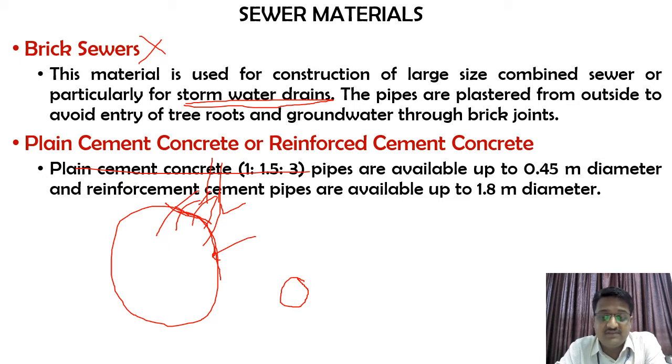But if the same thing is there with the sewers, then in due course of time the quality of these bricks itself may deteriorate, because of which the entire sewer pipeline may collapse, since the bricks will continuously start to absorb the contaminants. There will be formation of numerous acids and foul gases, each of which will have a detrimental effect on the brick material.